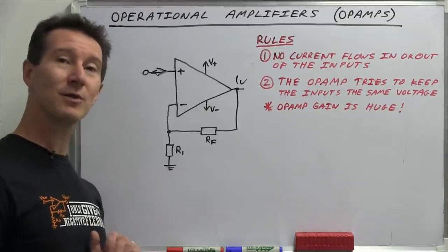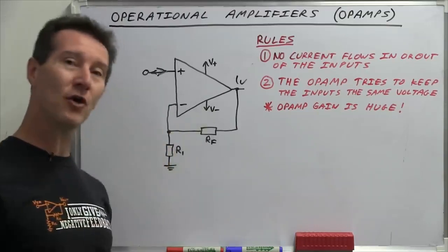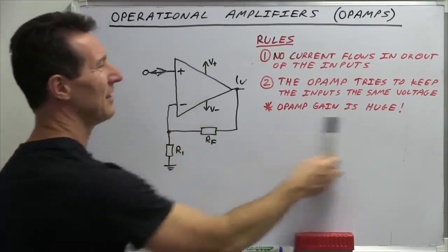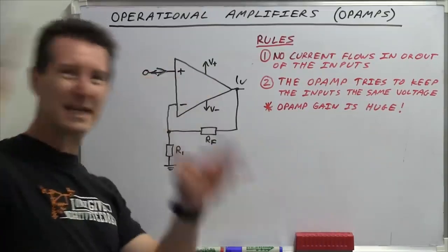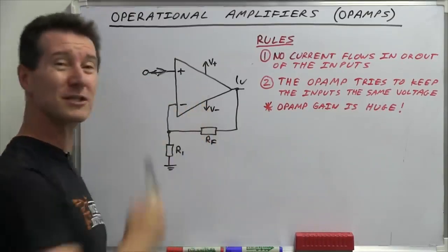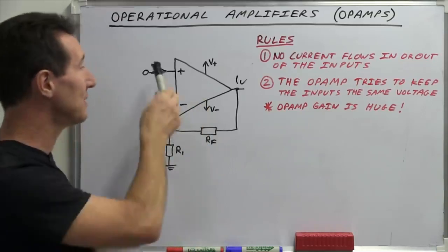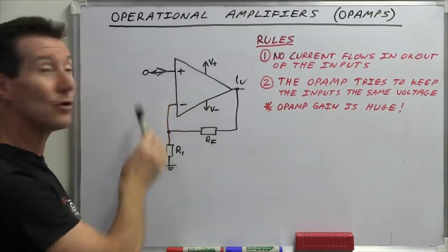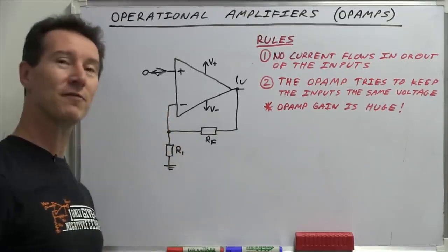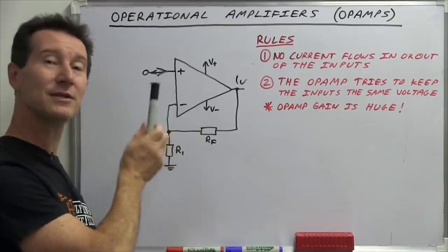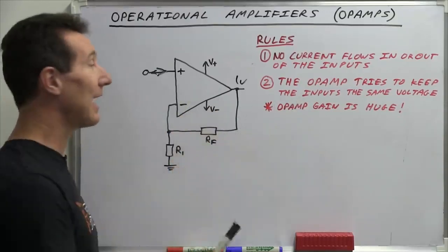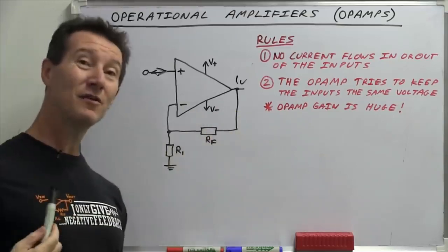Now the next configuration we're going to take a look at is what's called the non-inverting amplifier, and this is where we tame our op-amp beast, that huge unwieldy gain that changes everywhere with temperature, and it's horrible. Anyway, it's got this massive unusable gain as a differential amplifier, but as a single-ended amplifier, that's what single-ended means, you feed the input here and it's always referenced to ground. We can use this as a single-ended amplifier, and we can tame that gain by adding negative feedback on it.